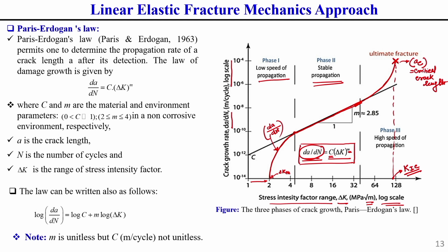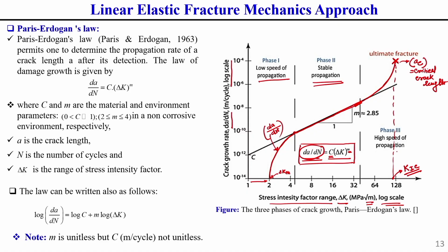So, in this middle zone, where the major portion of the crack propagation time takes place, Paris law is applicable. Okay. And this phase 3, which is the high speed propagation zone, takes very little time and suddenly catastrophic failure takes place. You should keep this in mind.